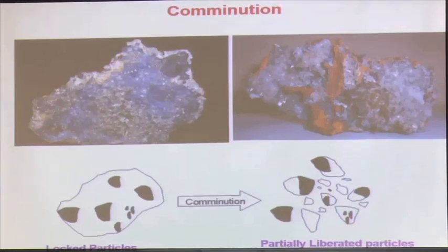What is the condition for optimization? That is your profit. If I separate them at this size and discard this, the particles which are free from the black particles, the relative grade will go up, the relative percentage of my black particles in that assemblage will go up. Now, will the metallurgist buy that? Can it give me 36.5% copper contained in that? If it meets that requirement, we restrict our size segregation to that size.